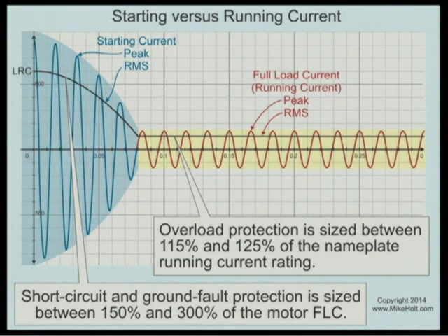Back over here in motors. Motor starts at locked rotor current. The higher the efficiency, the higher the locked rotor current. So it starts at locked rotor current, and then it starts going down, and then we have what? We start picking up reactance. The impedance goes up, and then all of a sudden now we're running at this.